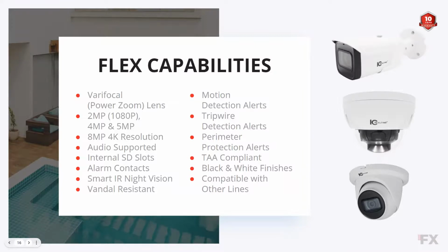These are not the same motors that you're going to find in a PTZ style camera that is meant for constant movement and zooming in and out. Varifocal lens cameras are meant to set it and forget it. Maybe make an adjustment later on if you choose to do so, but if you continuously zoom in and out using a varifocal lens camera, you are going to burn out those motors in pretty short order. So do keep that in mind. When it comes to varifocal lenses, it's allowing you to adjust your field of view, get that right coverage area that you need, and then leave that there.